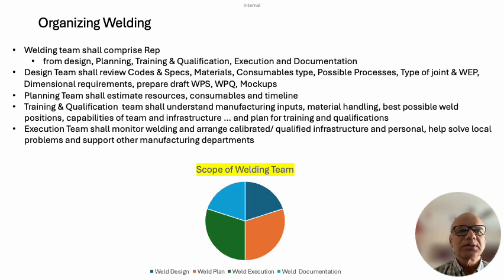The next step is to have a welding engineer in planning, as explained earlier. Now, since we have got an overall idea as to how the entire welding operations are going to be carried out and the proposed welding process, the joint designs have been already identified. Hopefully at this stage we also have clarity in the positions in which it will be welded. So accordingly we now need to start planning on the time frame, we need to start planning on the consumables, type, size, specifications, and which are the